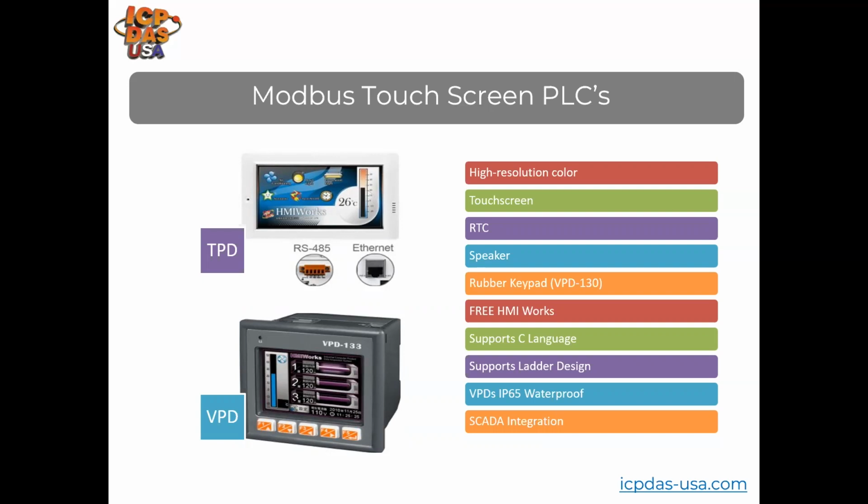Our TPD and VBD controllers can be set up as a Modbus master or a slave. We provide demo programs that show you how to read data from Modbus devices and access their registers, how to make the touchpad a Modbus RTU slave device, how to make it a master, how to use different widgets we provide, like the slider and the buttons and all that. We also have demo programs for showing how to use counters, display temperature from Modbus devices, read data, access different I/O information, control lighting, and more.